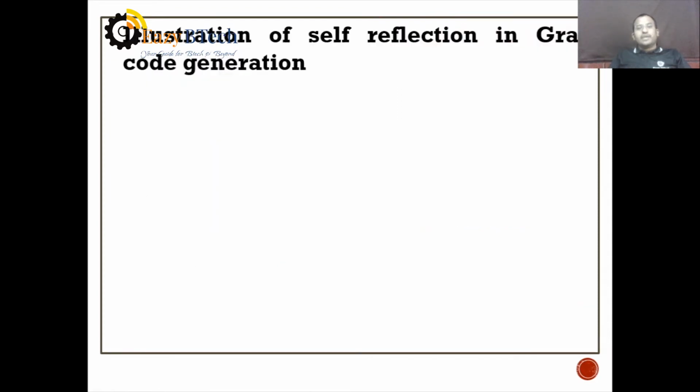Here we will see how to generate the gray code. For example, if you take 1 bit, what are the possibilities? We have 0 and 1, only these two. So now we have the 1 bit gray code, and we would like to get the 2 bit gray code. For this we take two 1 bit gray codes. This is the first half.